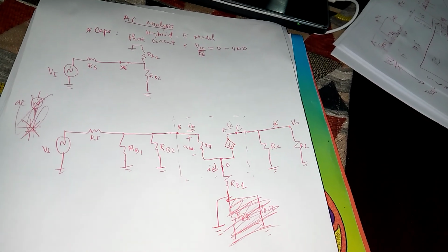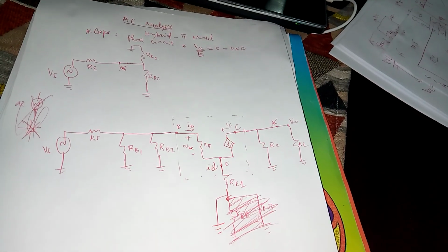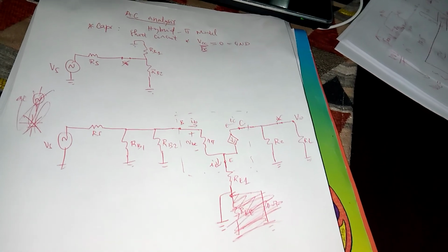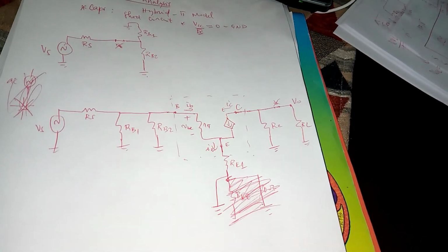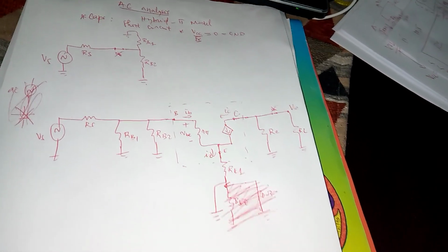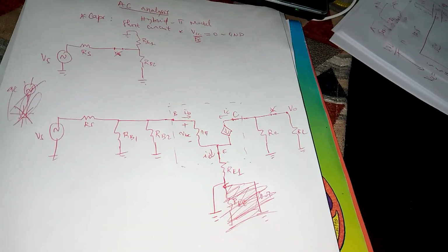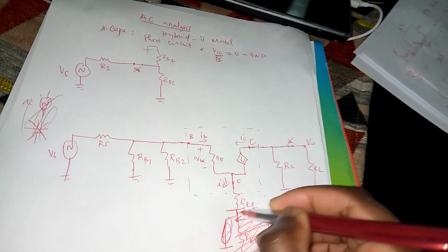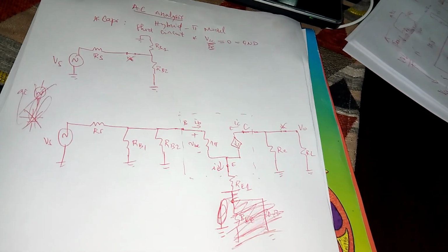And this circuit that you obtain at the end, with minor tweaks that I'll show you now, is becoming what we call the small signal AC equivalent circuit of the BJT amplifier circuit. So this point is grounded basically because RE2 is in parallel with 0 ohm.